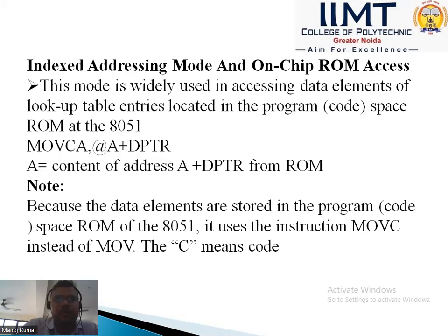The instruction MOVC is used instead of MOV. The C stands for code. MOVC is the command of index addressing mode for on-chip ROM access. This is MOVC A, @A+DPTR.